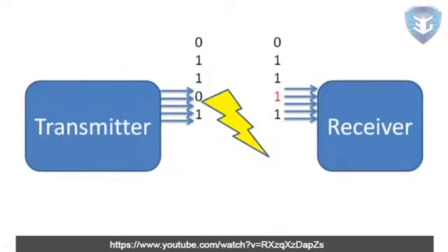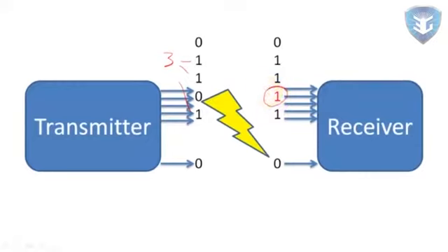Alternatively, we could require that the transmitting component send an even or odd number of 1s in its transmission. In this case, we would simply add one more bit to the transmission, and we would set this bit to be a 1 or a 0, depending on the number of 1s in the original transmission. If we want an odd number of 1s for the transmission, we would add a 0. The strategic addition of a parity bit in a code can increase the Hamming distance of the whole code by 1 and enables us to detect and potentially correct more errors.